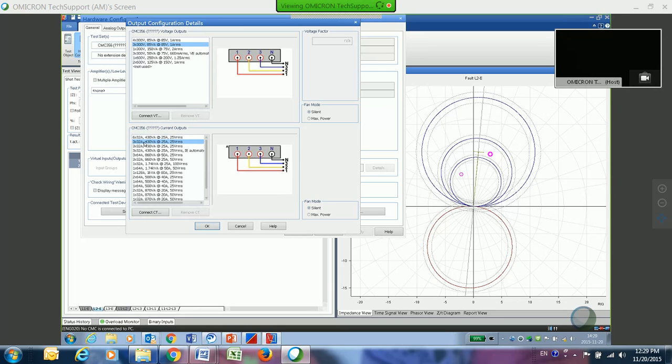The next 2, basically, if I've got a 356, I can specify whether I want this as channel A or channel B output off of my test set. I can do 3x64. 3x64 allows me to basically combine phase 1s on both channels A and B together and feed them into an input on my relay, and I can get 64 amps continuous out of this for 3-phase. And that's not a bad one to use a lot of times.